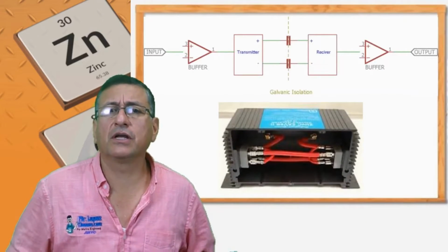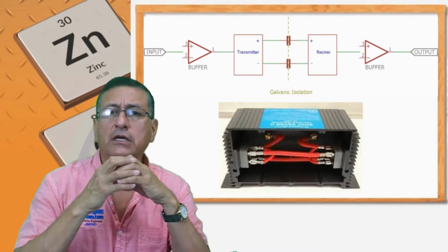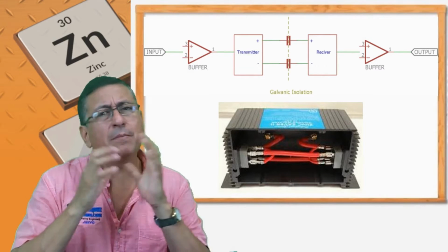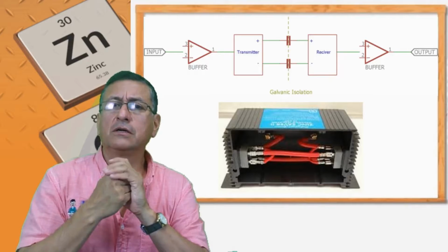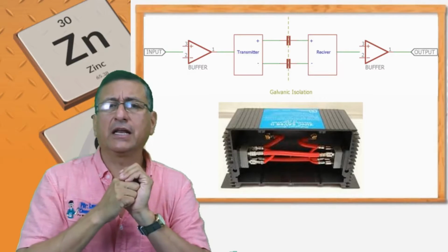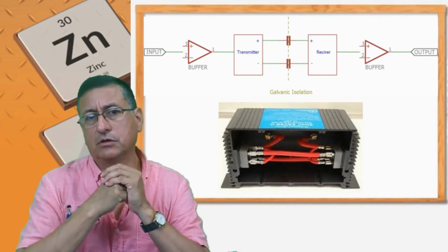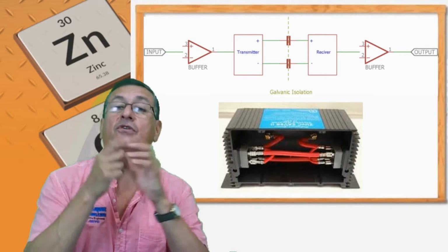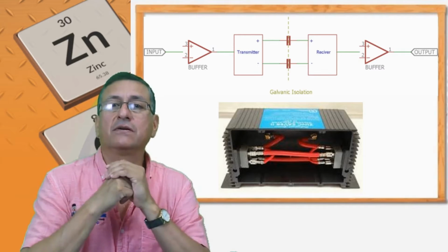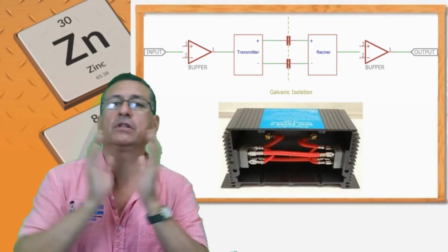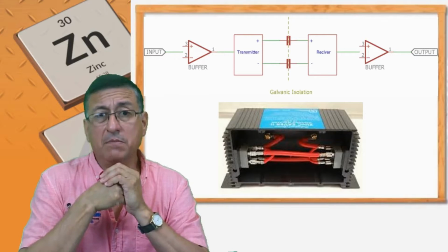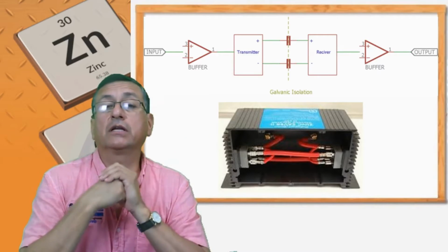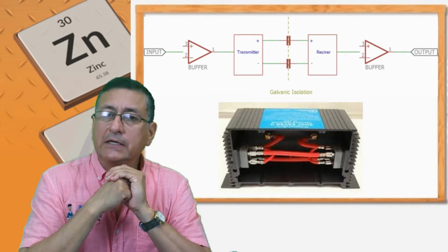Remember that the galvanic isolator inside the construction is diodes and capacitors. If you have diodes to block current, that current that you block, as you remember in electronics, should be stored in a capacitor, and the capacitor drains through the bonding. For that reason, the case of the galvanic isolator should be connected to the bonding. Normally, with the bigger galvanic isolators, the case is metallic, and that case should also be connected to the bonding. All right, my friends? Important.